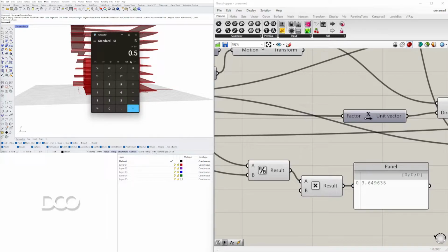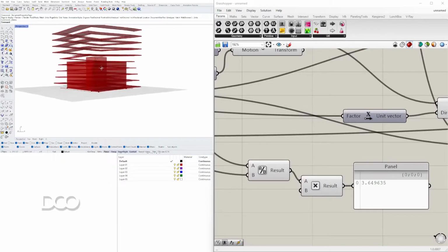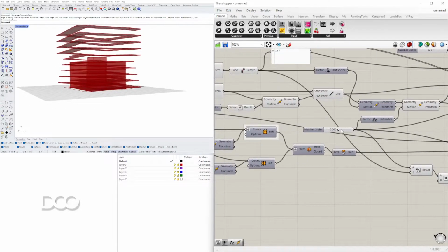And when we're talking about a slope, 3%, we'll do 1 divided by 12, which is 0.08, and that's the maximum. So if we move this over a couple, it's going to be 0.08 that we don't want to go over. So now here, it looks like we're probably okay if we increase this to more.